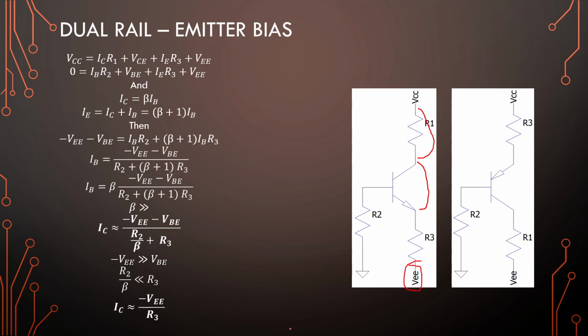value right there. Okay, so this bottom resistor and source will be responsible for our bias, right? And these top two will be responsible for our maximum swing. Resistor 2 will influence our input impedance and is basically just supplying a path into our transistor.